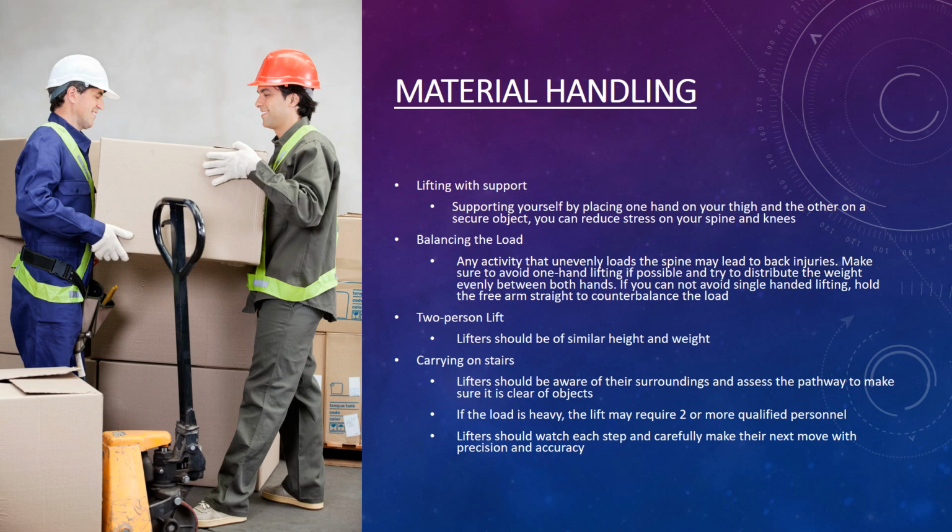Two-person lift. Lifters should be of similar height and weight. Carrying on stairs. Lifters should be aware of their surroundings and assess the pathway to make sure it is clear of any objects. If the load is heavy, the lift may require two or more qualified personnel. Lifters should watch each step and carefully make their next move with precision and accuracy.